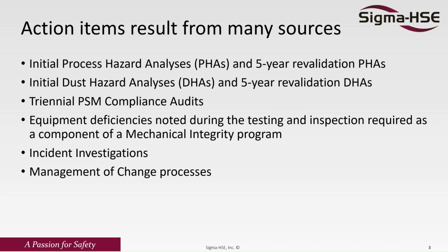You have your 3-year PSM compliance audits that normally generate requirements for corrective actions as well. As part of your mechanical integrity program, performing your periodic equipment inspections, you can come up with deficiencies and required corrections there. Incident investigations may identify corrective measures you need to take to prevent future incidents from occurring.